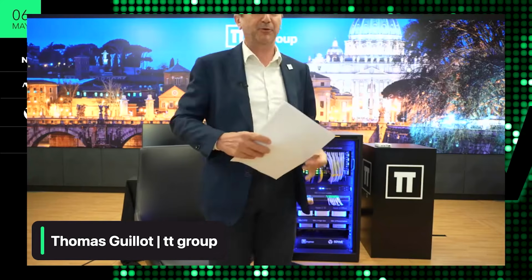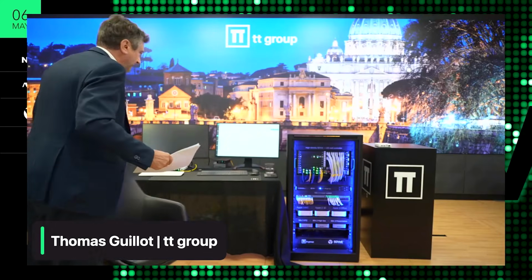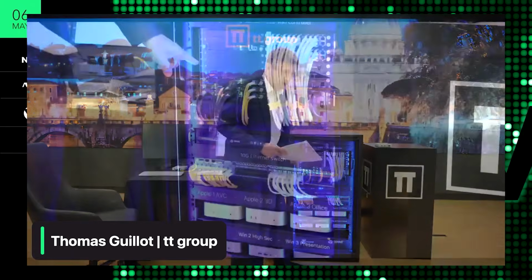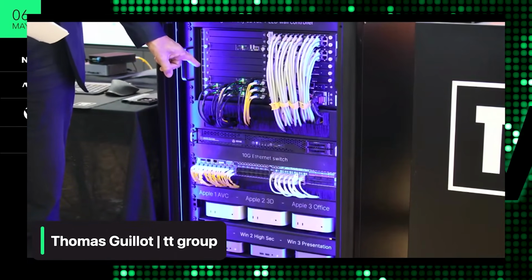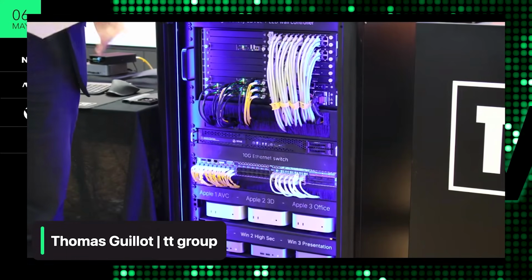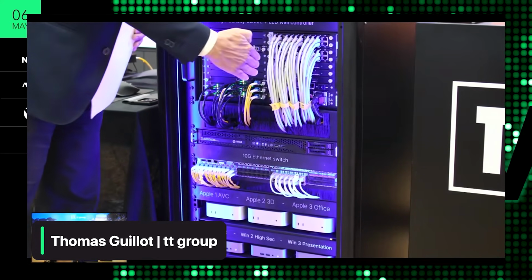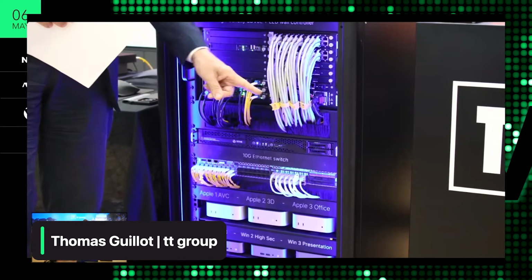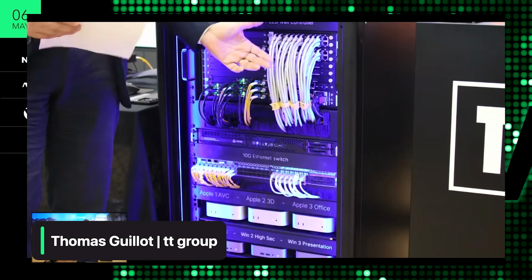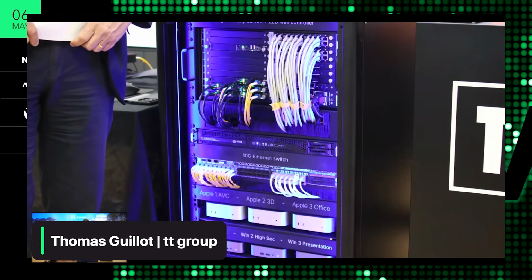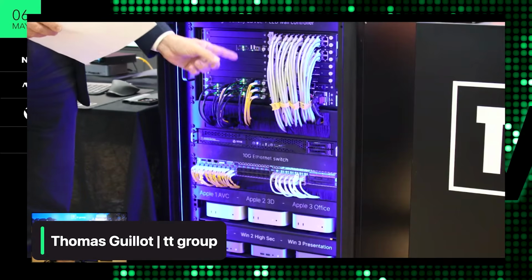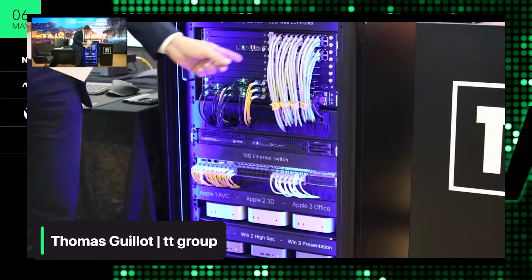And we are driving it with the rack that I will present you now. We are driving it with the H5 controller from Novastar. On the right side, you see all the output cards that are connected to the LED wall. As you can see, this is not a straight HDMI connection. You have actually 36 cables going to the cabinets of the LED wall behind me.